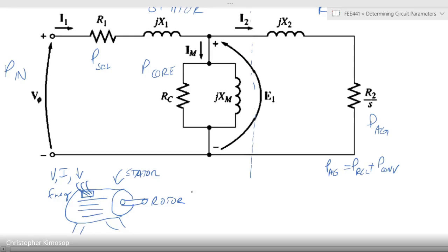You can also, to some degree, probably measure the speed of the rotor shaft. That is the actual mechanical speed, which we call N, right? Now, given the voltage, current, and frequency, you would also be able to get various other elements. Some of the powers you can get, for example, input power. You could also get synchronous speed. You could get various aspects like that, okay?